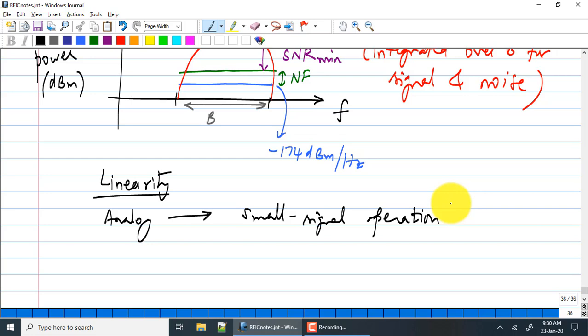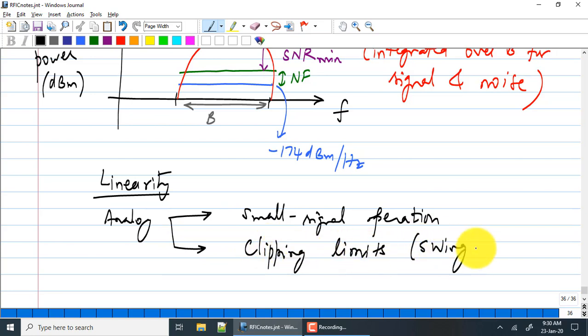strongly audible distortion. Eventually when you start clipping, when you hit the limits of the swings inside your circuits, you will start clipping the signal, right? And that is the second one that you mentioned. Now, what happens when you start clipping?